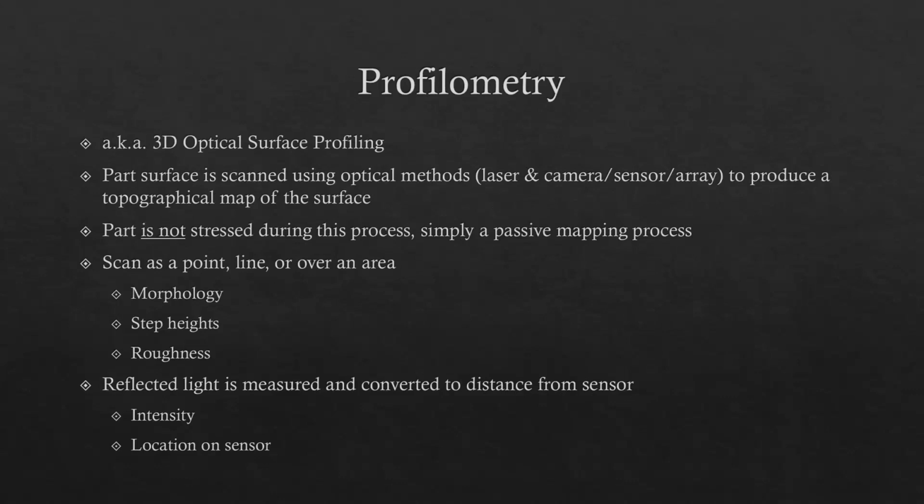This is the one I was talking about. When we had planes fly through hail, we use this. We were able to put profilometry equipment up and essentially take pictures of the areas of the skin, and it would create a 3D map that we could then send with measurements, with numerical values for areas, depths, shapes of all these different dents. And we could then send that to the aircraft manufacturer to get engineering approval or to get a repair drawn up.